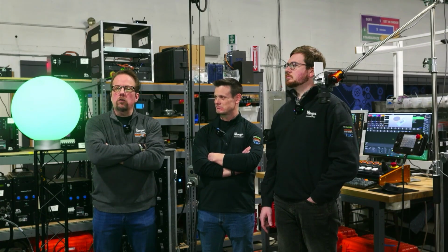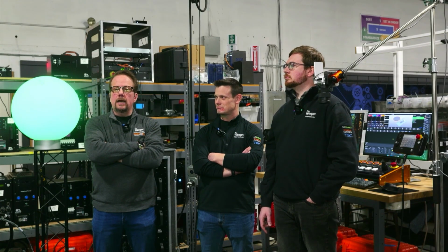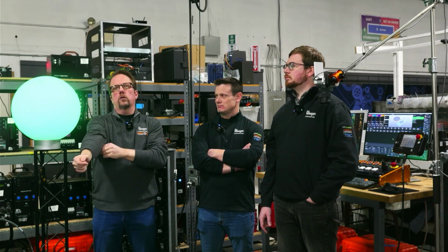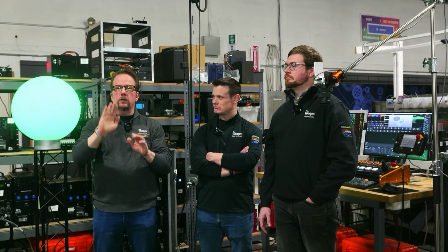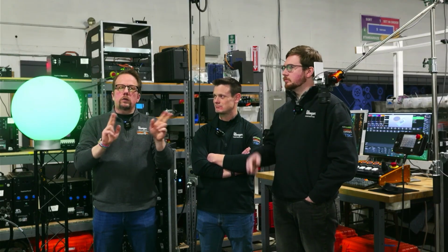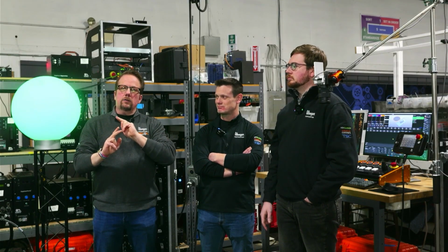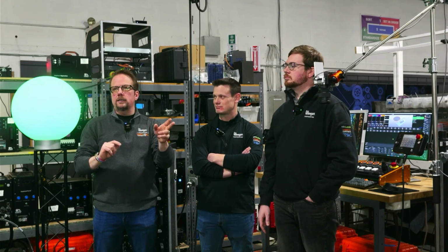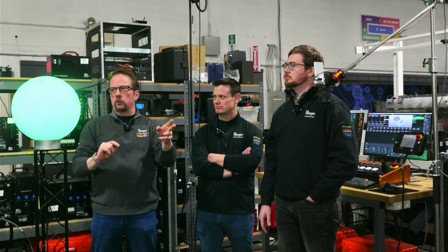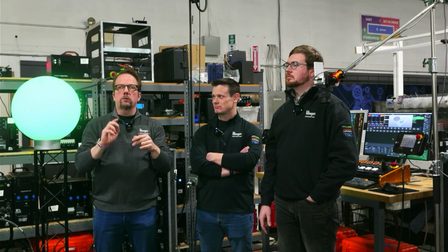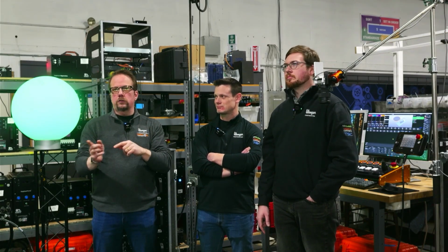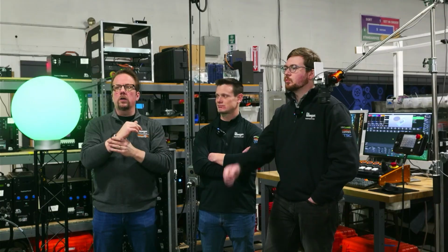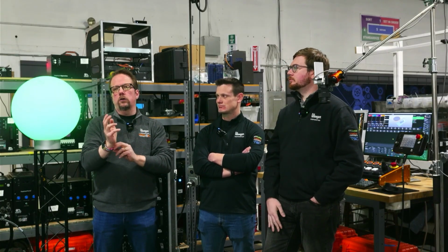The way those are all ID'd, we do limit the number of IDs, because for each button that you press, there are two things that play there electrically. We have the safety circuit, but then we also are running a CAN network through every emergency stop input, so that we can register which emergency stop was triggered and signal that back to Spikemark. So we artificially limit that to 127.